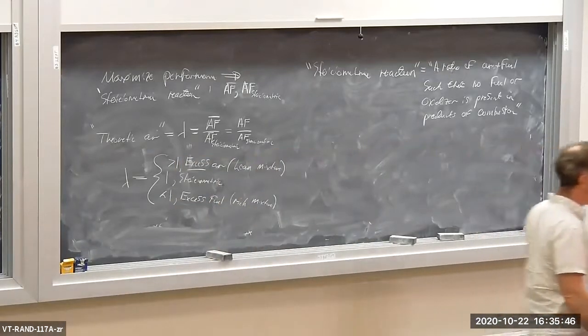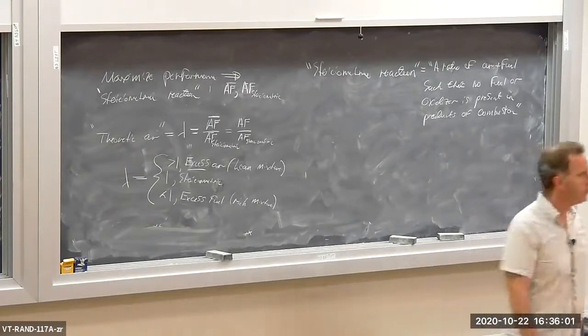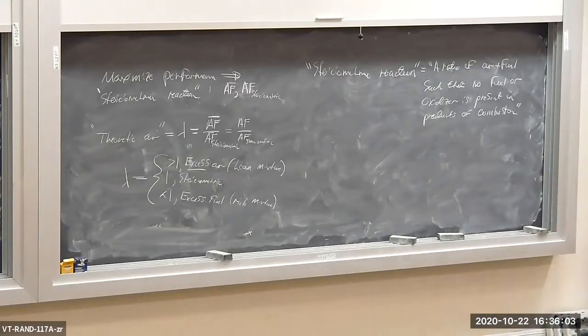Slightly better fuel economy, more power, better performance and acceleration. The cost was, of course, a reduction in performance in terms of emissions. So typically having a rich mixture means that you have more carbon monoxide and hydrocarbon in the exhaust, and that's not so good when it comes to a clean environment, okay?